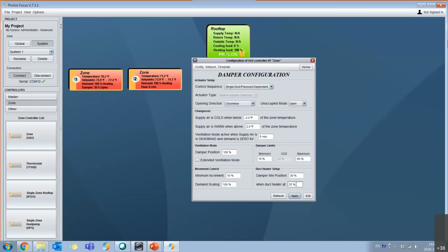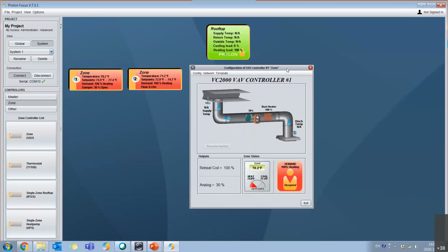And in case it was a modulating three-way valve, so now it's not just open close, but it's a ramp, then we can say, once we've achieved 25% of the output, only then do we want it to go to the minimum reheat position, which would be 30%. Okay, so I hope I was able to answer that question.